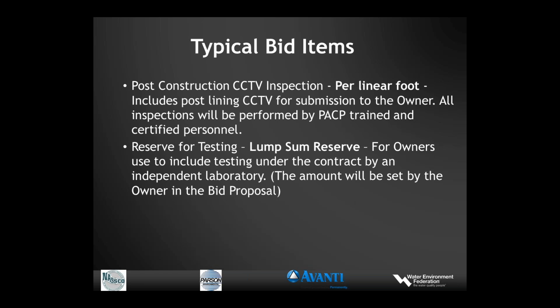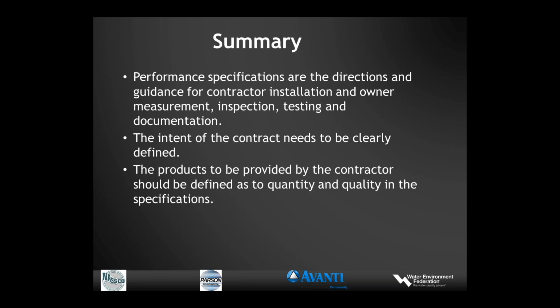And then finally, post-construction CCTV and a reserve for testing. In summary, I think this first bullet summarizes where we're trying to go with these performance specifications. But these are the directions and guidance for contractor installation and owner measurement, inspection, testing, and documentation.